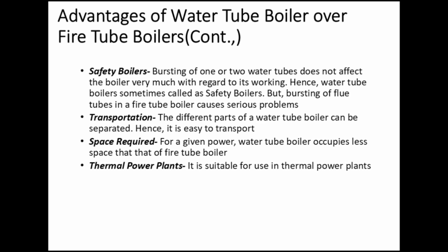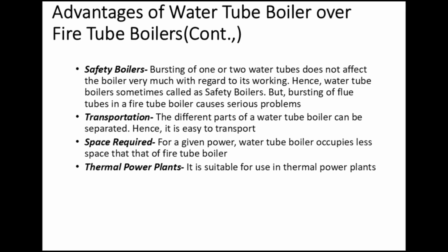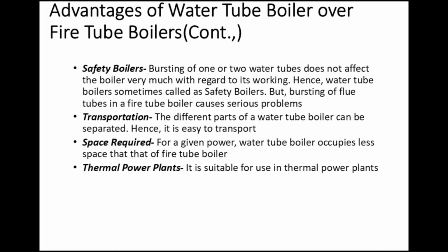Advantages of water tube boiler over fire tube boilers. Steam pressure. Steam can be generated at very high pressure in water tube boilers. Heating surface. In water tube boilers, water is contained in a large number of tubes. Hence, heating surface is more than that of fire tube boilers, thus evaporation rate increases.